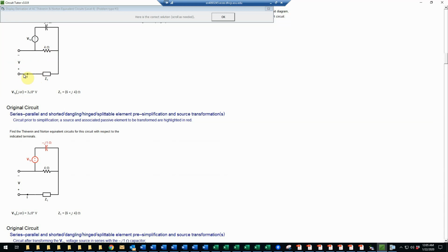That's why we have the I symbol down here to remind us that in general there will be an output current unless these happen to be open circuited, which would be unusual. So because there is a current going here, coming back here, these 2 elements will not have the same current. They are not in series, and it's very important to remember that whenever you have terminals present in a network, as we originally discussed in the series parallel with terminals tutorial.